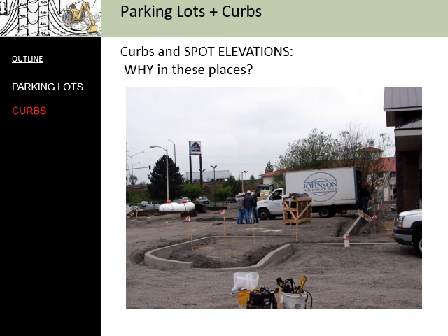So here we have a slightly simpler example, and we know that we're going to need a spot elevation where we have a corner, where we have tangents hitting curves, where we have the top of a change in elevation, the bottom of a change in elevation, we're going to talk about those more later, or where we might have a low point where we might have water draining into some sort of retention system.